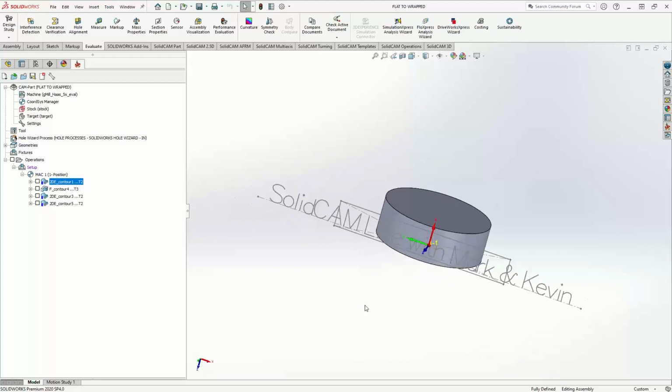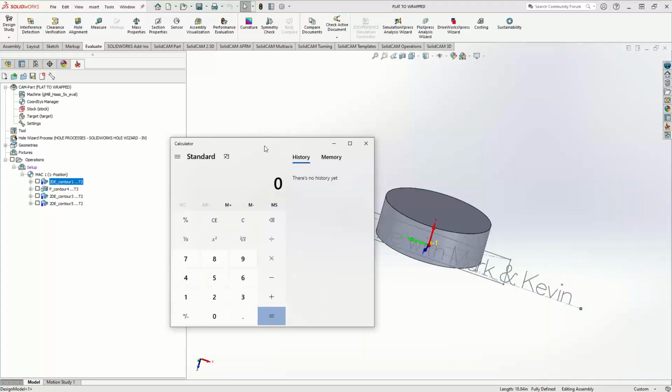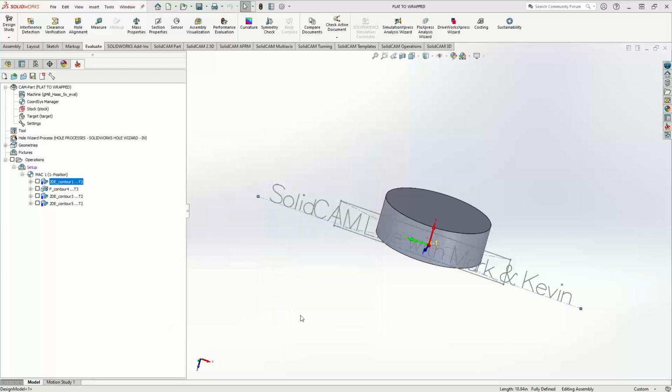Well, now, couldn't we, so if, go ahead and click on the edge. What is the diameter of that? This is 6 inches. So couldn't you just make that line 6 inches long? No, because it would not wrap all the way around. So what you've got to do is know the circumference, because what you're doing is wrapping this all the way around the circle. Gotcha. So that's why the length of this line is actually 18.84. 6 inches times 3.14, 18.84.